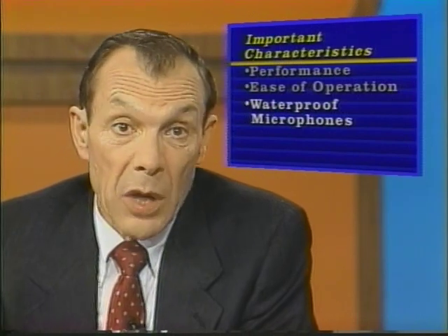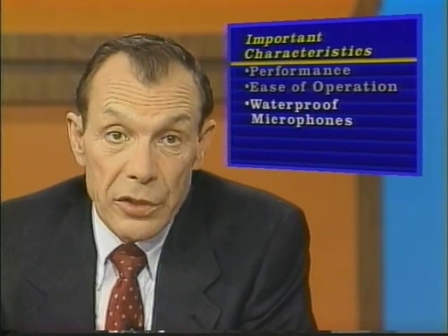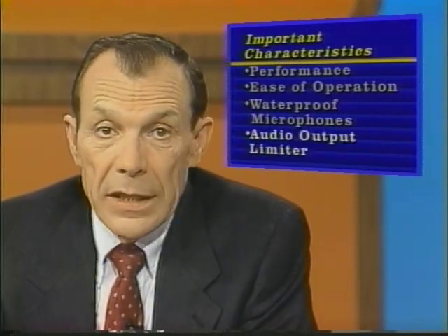To evaluate acoustical instruments for purchase, the performance of the instrument is of course important, but you need to look at several other things as well. Look for ease of operation, waterproof microphones, and most of all, make sure the instrument will not hurt you. Some of the acoustics on the market do not limit the audio output to the headphones. Unlimited output could change your hearing.